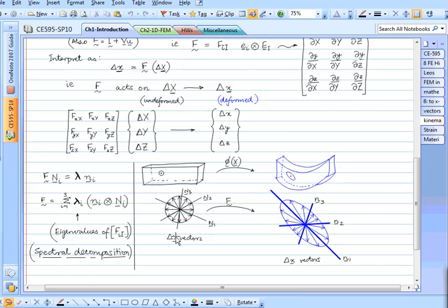In all of continuum mechanics, the only mode of deformation is that if you go to a point and draw your small set of vectors, the only possibility is that it will deform into an ellipsoid. There are no other modes of deformation because F is linear, F is a matrix. If you express F as a matrix, it will have some eigenvalues, and those eigenvalues are the stretches acting in these principal directions.